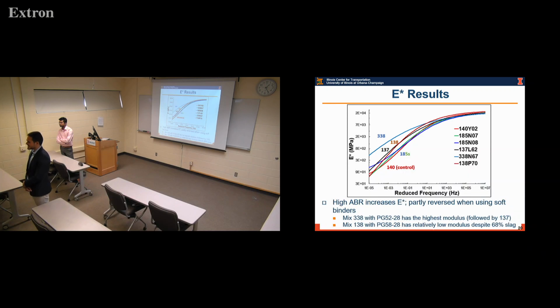I have a question for Jose. About the air void correction equation, what is the appropriate range? Because I think the paper you published has an appropriate air void range that is different from what Maxwell came up with, so I don't know which one we should follow. Right now, we recommend over 8% air void content. We should try to avoid the lower side. From the lower side, we haven't put a minimum range in that case.